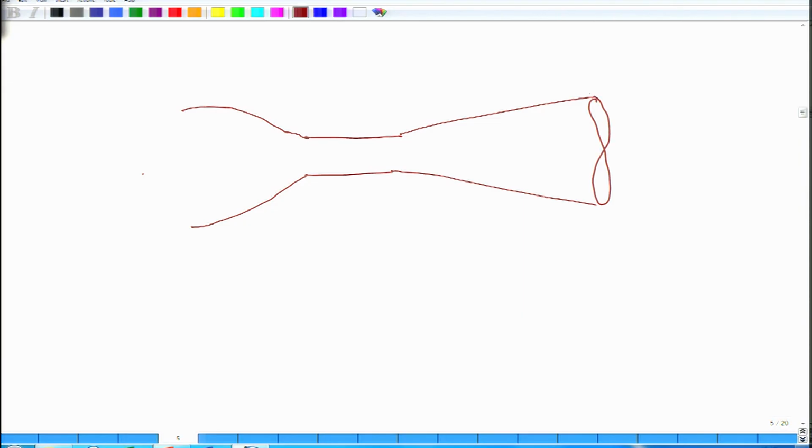What is the wind tunnel? The first and foremost, please understand what is a wind tunnel. A subsonic wind tunnel looks like this shape. That is, a convergent portion is there, and from the convergent portion there is a constant area passage, and then there is something like this diverging passage, and either at the upstream or at the downstream generally there is a blower which essentially rotates and it creates a suction effect, and then the flow takes place.